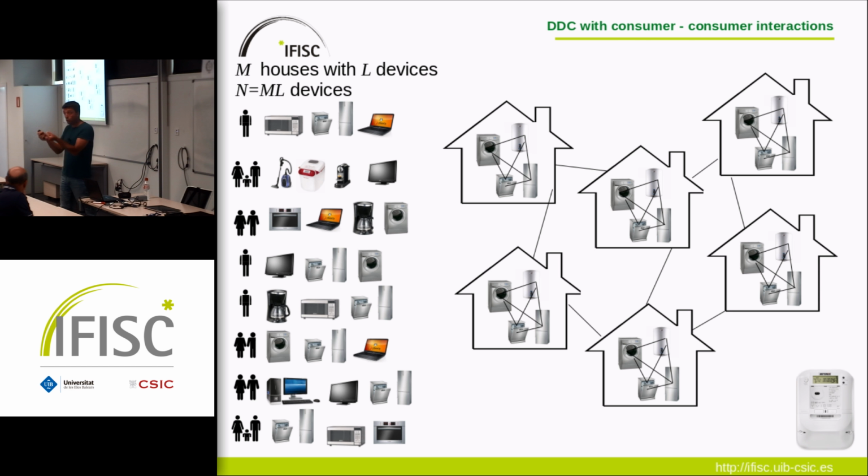We do this such that this is not helping to control the frequency, but helps to keep the consumption of a house constant. Because if this has to switch on, it waits until that one switches off, then this switches on, and the total power stays constant. So this is not helping to control the frequency, but it reduces fluctuations. And then the control of the power plant will adapt to that amount. So that's what we have implemented.